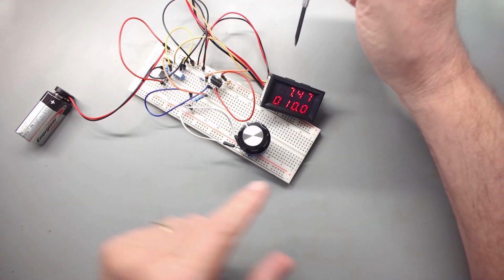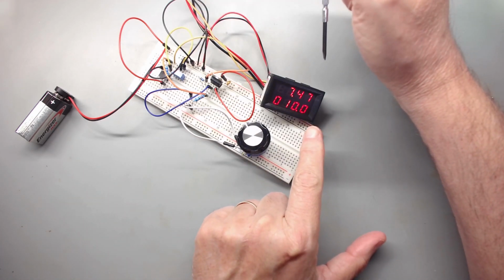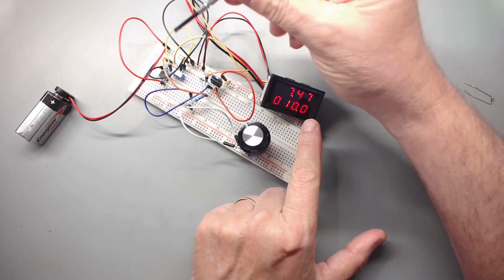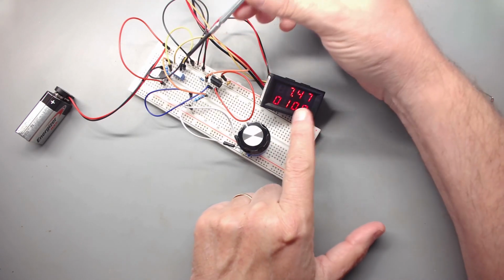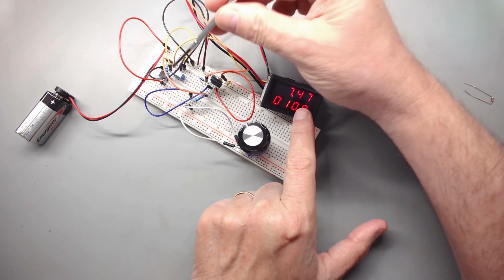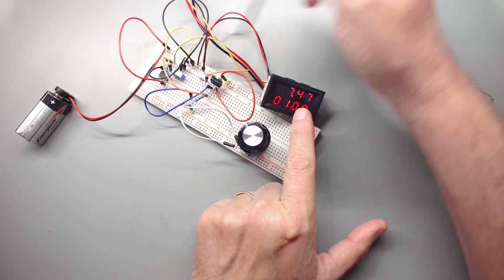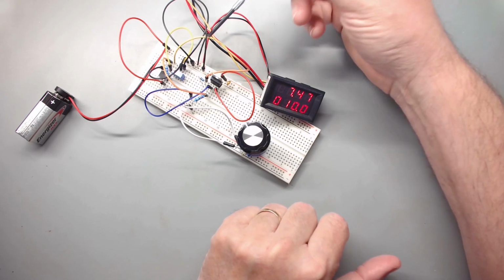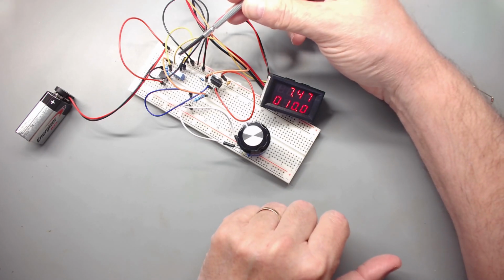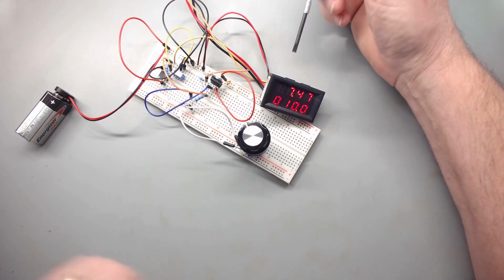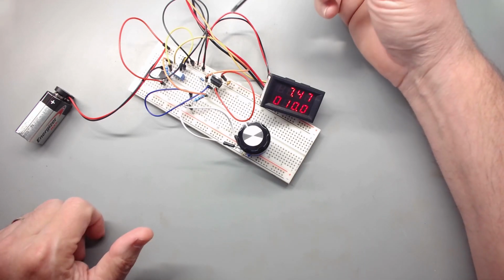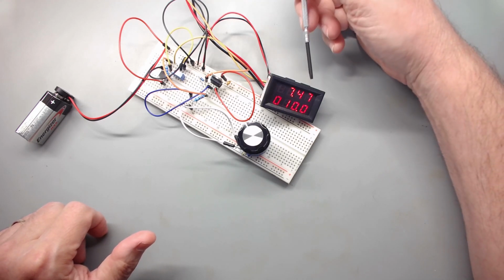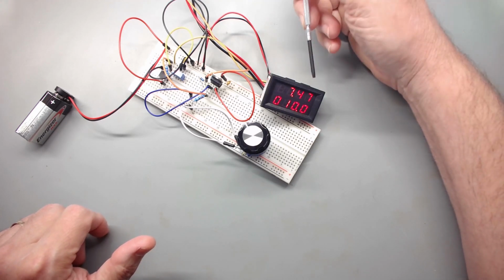And then what I did is I set it up to say, I think I did 0.8 volts. Yeah, I think it was 0.8 volts. And then what I did was this voltage was slightly off, so I adjusted this trimmer until I got exactly 8.00, thereby calibrating my 10 times gain. Then I turned around and did tests by adjusting my power supply in different voltages to see if it stayed 10 times, and it precisely did.